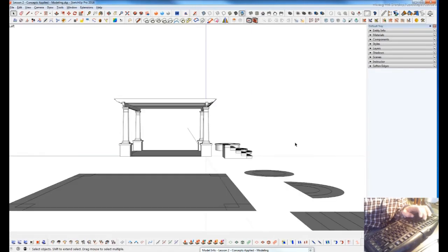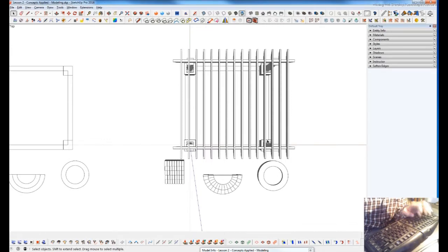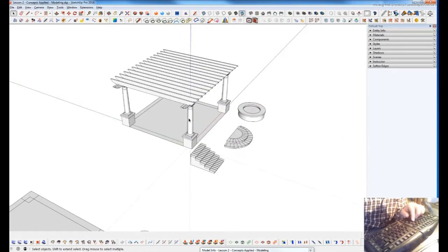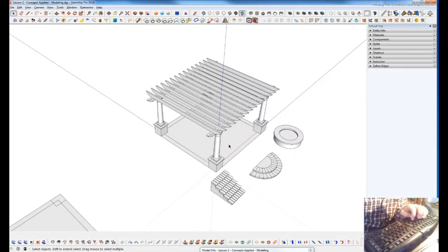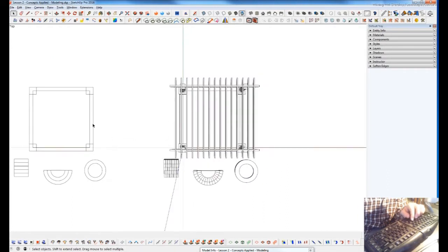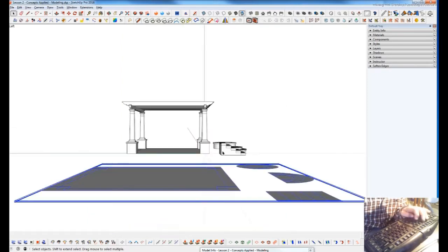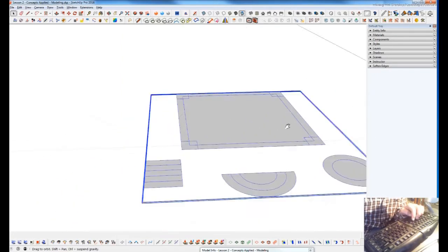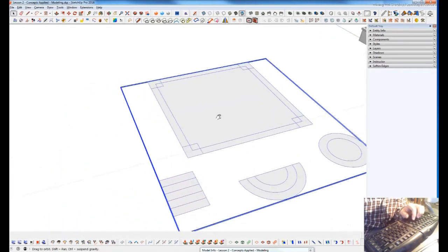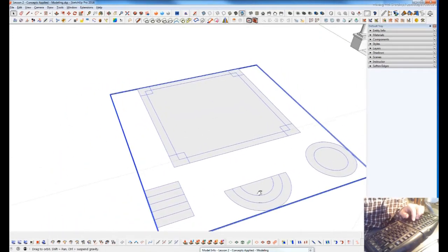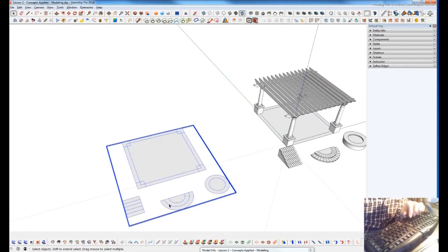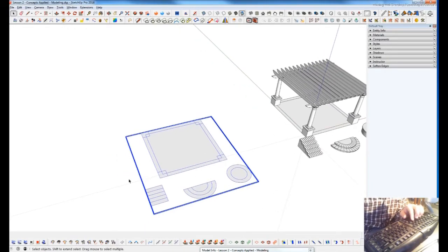I can do that very quickly without looking, and it helps me switch the camera if I need a different camera position. I also have zoom extents, which I can get to depending on what's selected, and then change the camera. It helps to center things, so now when I'm orbiting, everything's in the center. Navigation is a big part of speeding up your workflow as well.